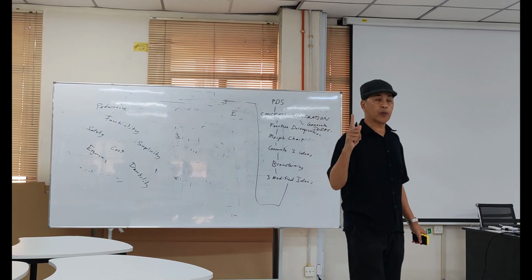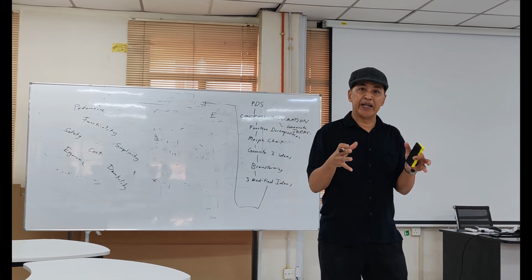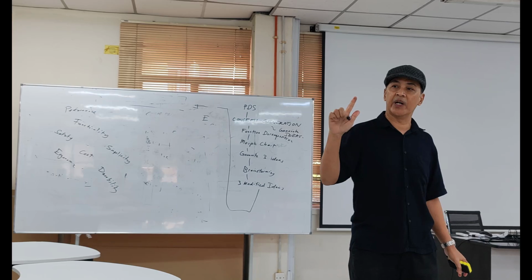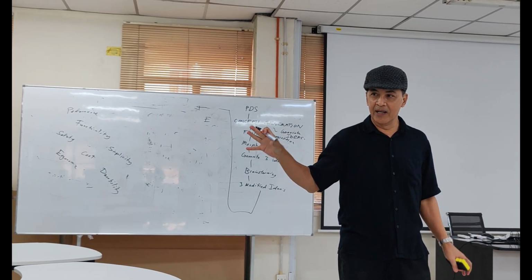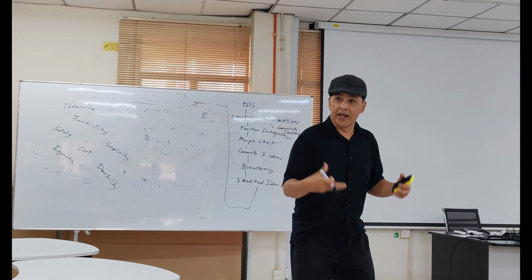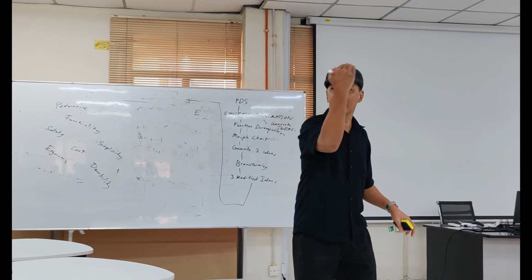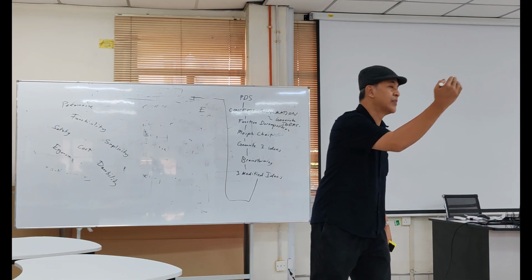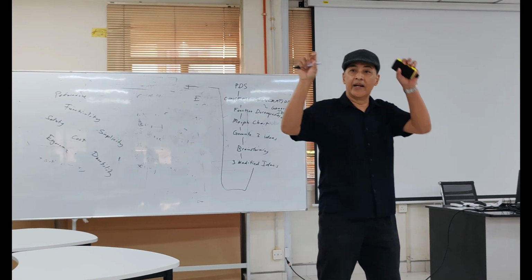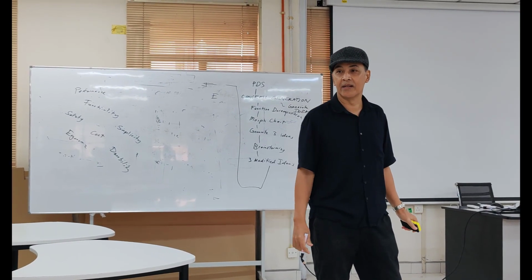Okay, one way, the best way through experience. You generate ideas. After you have done the PDS, I need you to generate ideas, right? We have a systematic way to generate ideas using function decomposition and a morphological chart. First function decomposition, then make a morphological chart, then you produce ideas. The ideas that you produce are based on the function decomposition, clear or not? You remember function decomposition, you have a sequence, a flow chart. The keywords from your function decomposition will be your criteria.